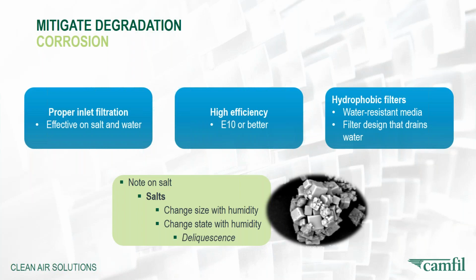When it turns to a liquid, that's where it becomes imperative that you have a hydrophobic filter, because now I'm not trying to stop, collect, and retain just a solid particulate. I need to deal with a droplet or a liquid. Some media, particularly older commodity level media, are not very good at that. So we'll have a saline saltwater droplet percolating through the media that will now be ingested by your machine, and become one of the enemies that creates a corrosion issue.